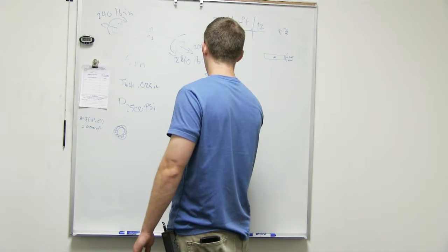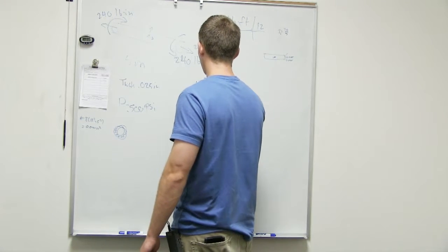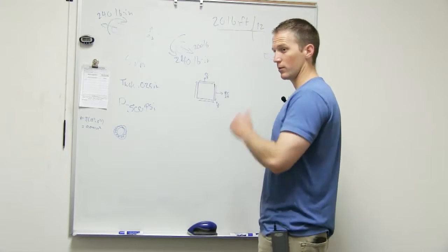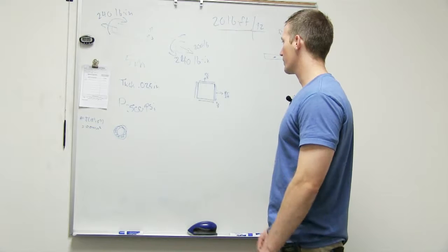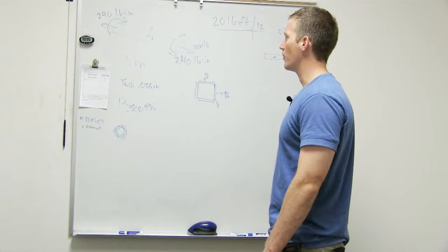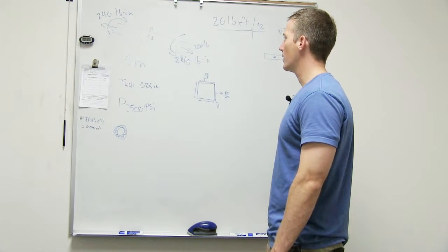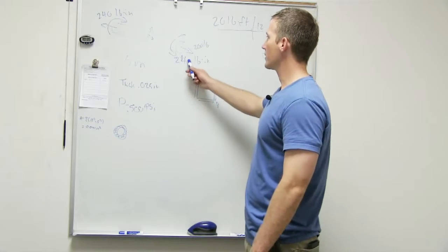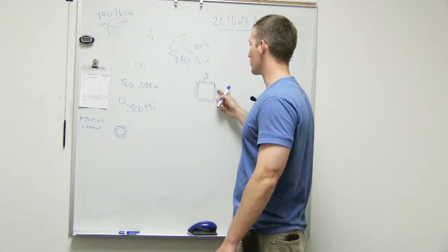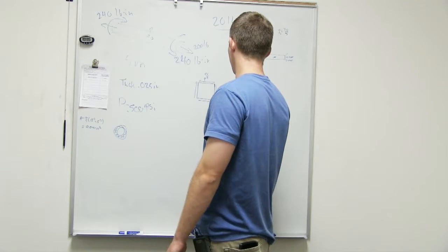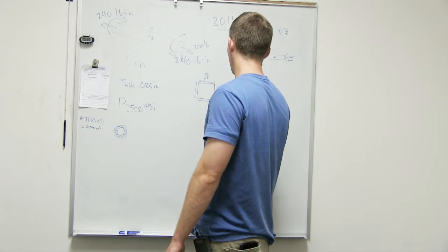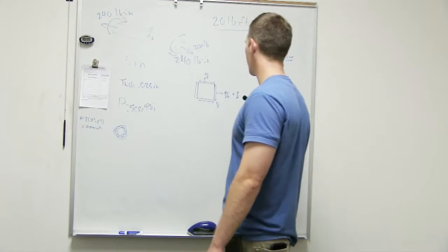Well, don't we already have it? We have the torque, we don't have the stress. Oh, okay. And that's going to be a negative number. It won't matter much. So the 240 is creating shear stress on our stress element, and then the 200 is acting in that direction, in conjunction, P over A.